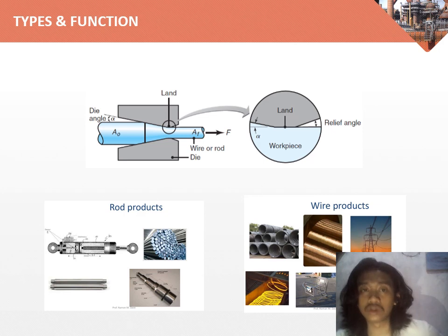The tube process is similar to bar drawing, except the beginning stock is a tube, and it is used to decrease the diameter, improve surface finish, and improve the dimensional accuracy of the products. The products of this type of drawing are such as rivets, screws, and even springs.